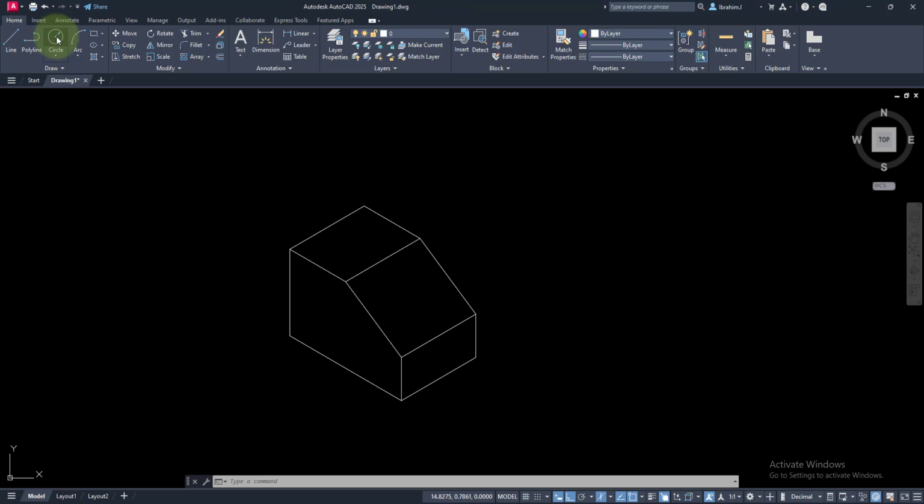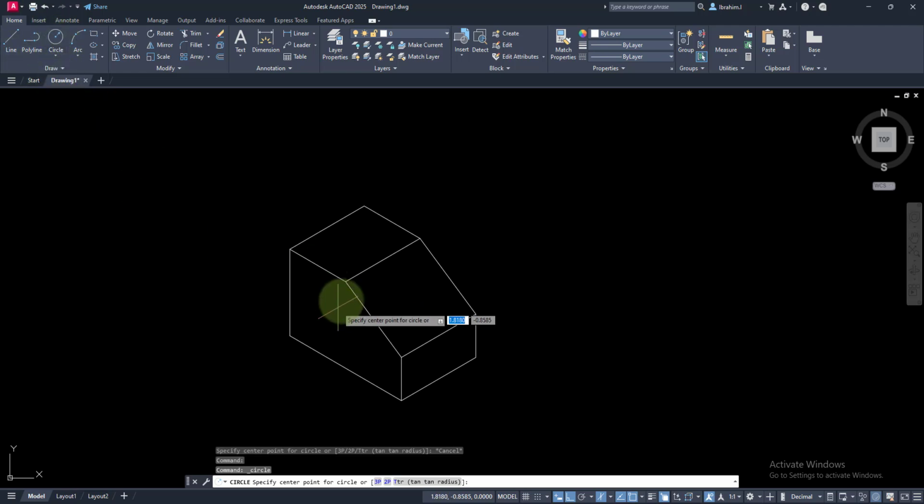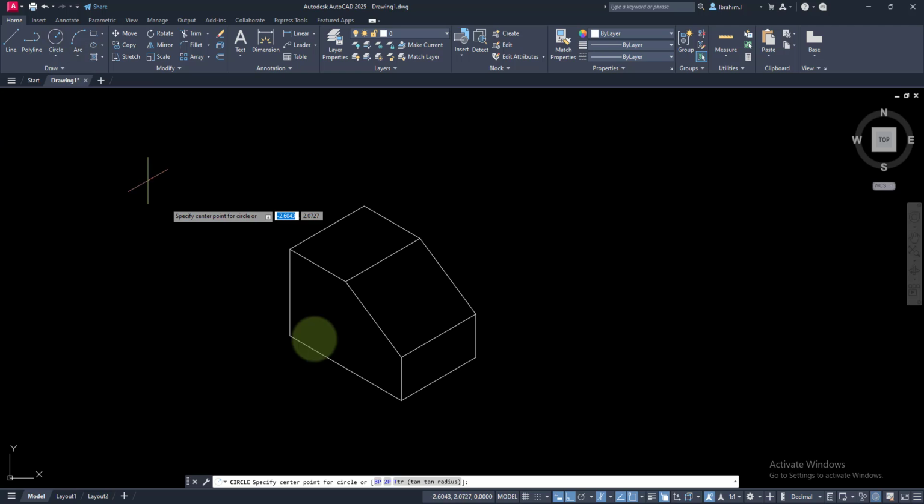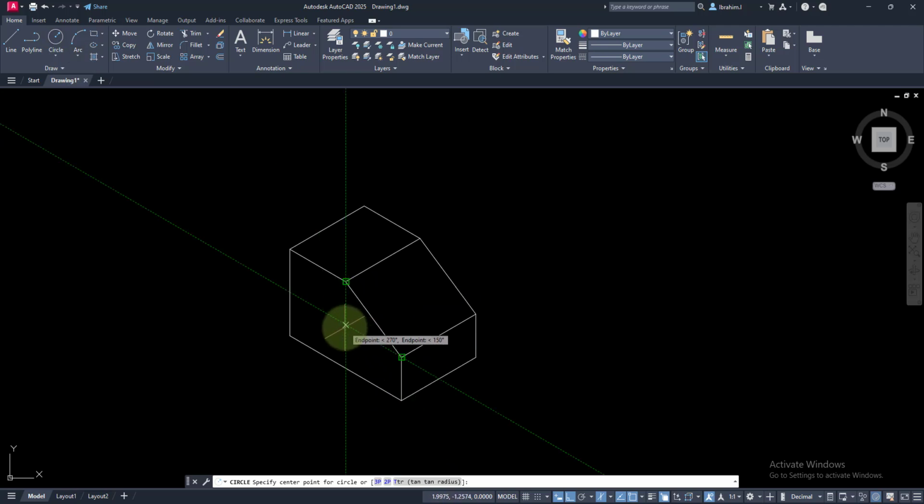Now if you try to recreate a circle center radius here, it will give you a lot of problems, because on isometric view, circle won't give you what we are looking for, right? Circle would not give you what we are looking for. Are you guys with me? Circle wouldn't align with the perspective. I'll try it out for you, because again, if you don't make a mistake, you don't know what is happening. So I'll connect it. Can you see, using my object snap tracking, if you are not seeing this line, there's something off on your line.